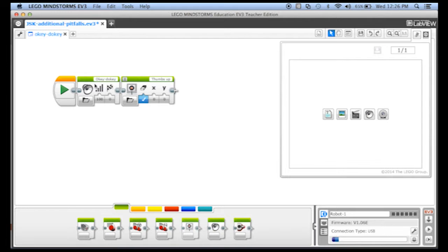You can actually change that on the sound block. If you look at this third menu here, drop-down menu, it says play type is 0 with this little picture of a checkered flag here. If I click on that, you can see 0 says wait for completion. That's what we've got selected. That's the default. You can also say play once, which means start to play the sound, but then go straight on to the next block while you're still playing it. And there's also repeat. But I'm going to leave this at wait for completion.